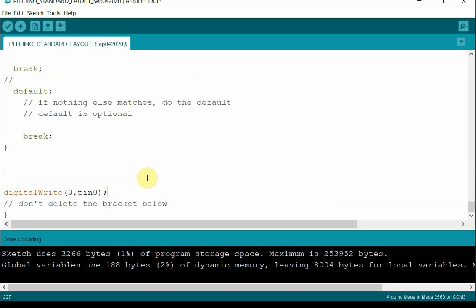So the difference here is that I don't update the outputs until the very end of the program. The cycle is it will loop back around at this point, go back up to the top of loop and repeat it. So by doing this, I'm not updating things on the fly. I'm going to hold off until the very end. And this is how PLCs operate.